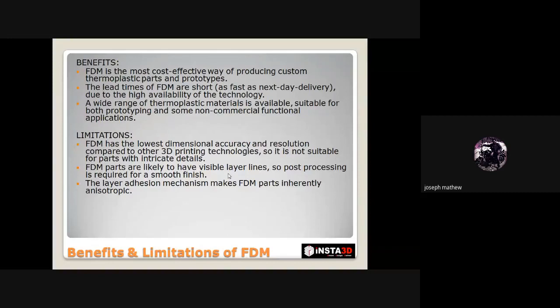Coming to the post processing techniques, you can use various methods to coat the FDM printed component. One is epoxy coating. You can mix the epoxy material and start coating the FDM component and use fine grit sandpaper to finish it. Or you can use normal acrylic paint to coat over the FDM 3D printed component.